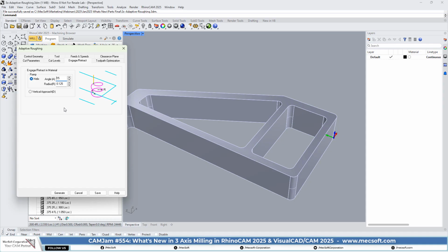We don't want it to stop at all. So in most cases, at each cut level, you'll see one helical entry and one exit. You may see areas where the tool may have to rise and transfer, to get down to another area. You may see that, but even in those areas, we add arc motions to facilitate the high-speed cut pattern.